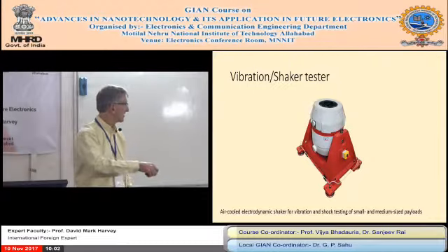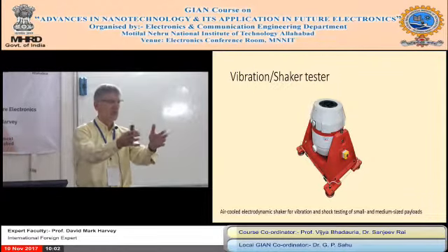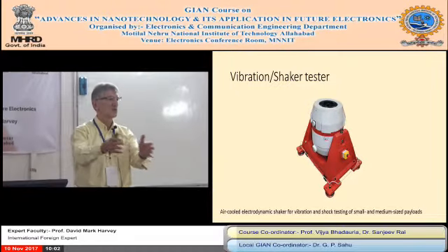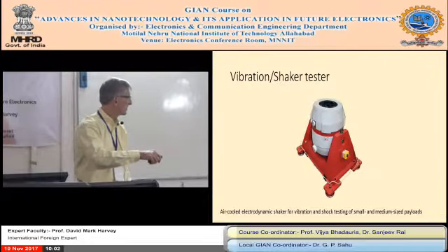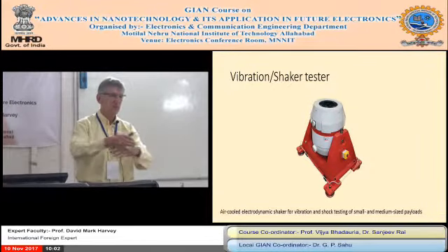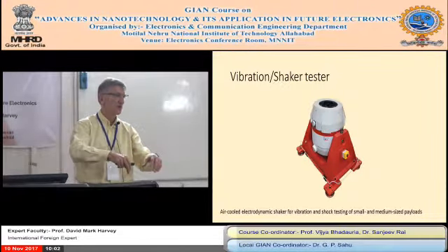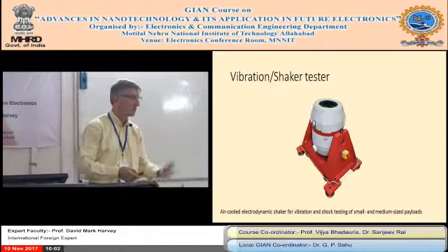Inside there, you've got a big coil and sort of a piston like a motor, and you can vibrate it at frequencies from, say, a few hertz up to a few kilohertz. So how you work it is you put a test block on the top, maybe aluminium, and you put your circuit boards in the test block. Again, you can power your board while you're vibrating it, or you may just want to vibrate it and see what happens to the solder joints, which is what we're doing.